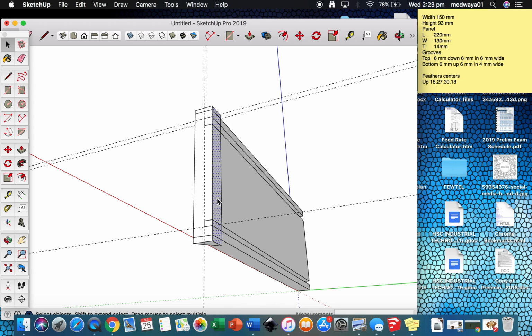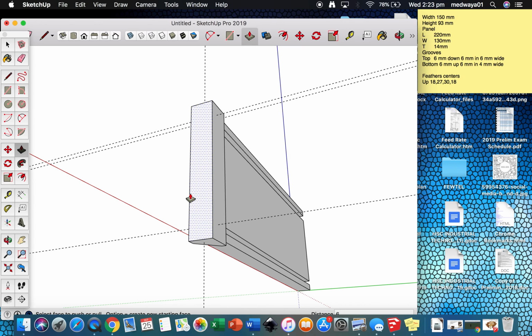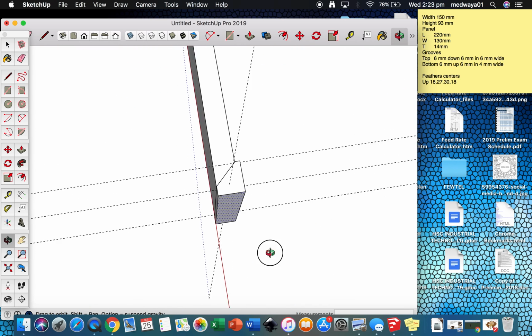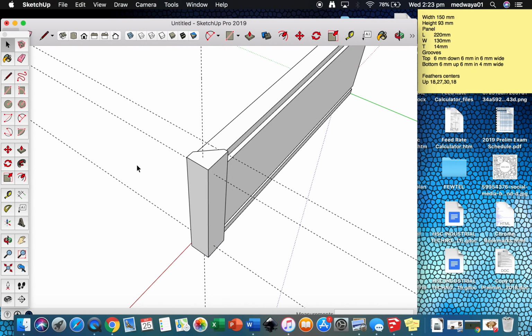I'm now going to select that side. I'm going to pull that out a bit to make it bigger. I'll select that side and pull that out and make it bigger as well. Again, O for orbit. It's bigger than the whole thing. So I'm now going to make it a solid object so this next process will work. So triple click, make it a group, and then use the Trim tool and click on that one. It's now trimmed it. Delete, done.